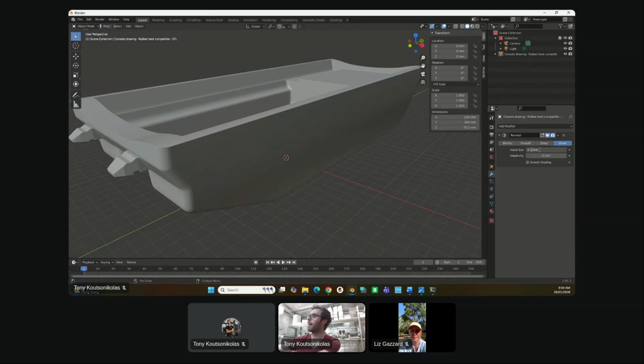But this will totally depend on your texture. Like if your texture was really small, you have to make that small. You've got to make it similar to or a bit smaller than the actual texture size. But if the texture is quite big, say the texture was like big circles that are 5 centimeters, then your voxel size might be 0.5 millimeter or something like that. So it just depends how big your texture is. The smaller your texture, the smaller your mesh needs to be to accurately represent it.